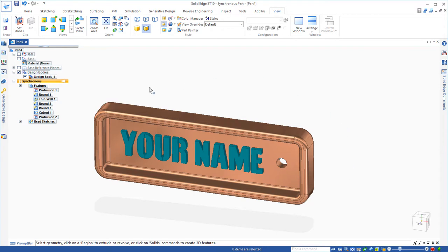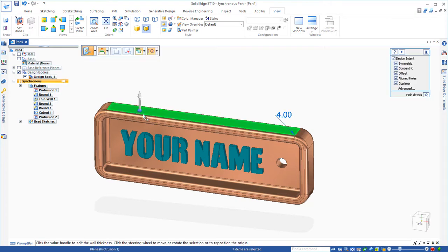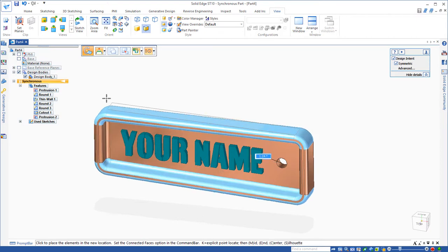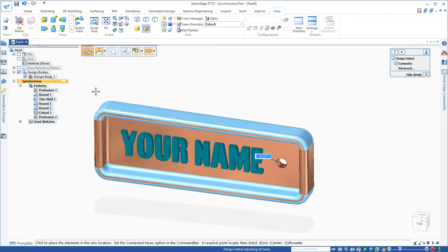Maybe you want to add an angle. If you click on this and you grab the origin of what we call the steering wheel, and if I take it down to an edge or take it down to the center of the hole, let's do that. To the center of the hole, you just touch the edge of the circle and it will snap to the center of the hole. Now you can see this torus on the steering wheel. If I click on the torus of the steering wheel and begin moving my cursor, you can see that I can add an angle